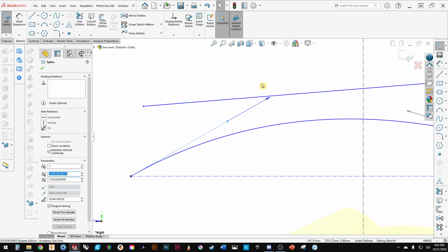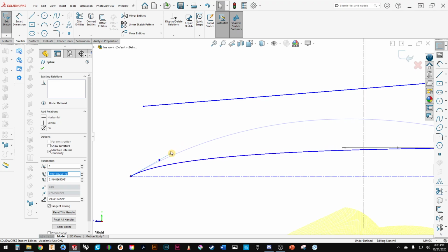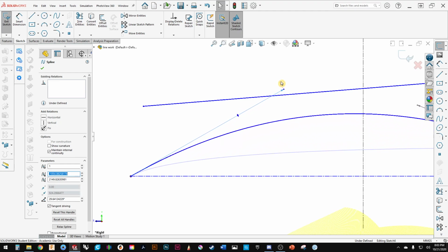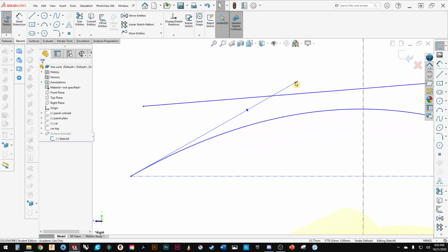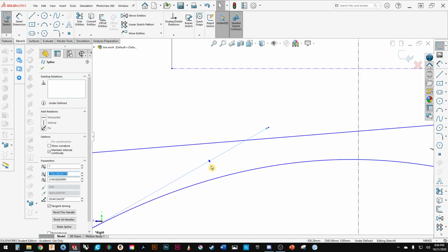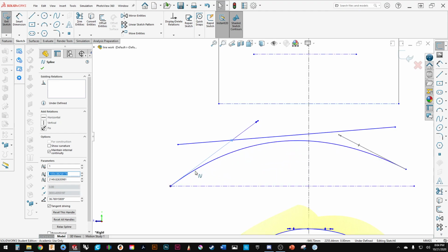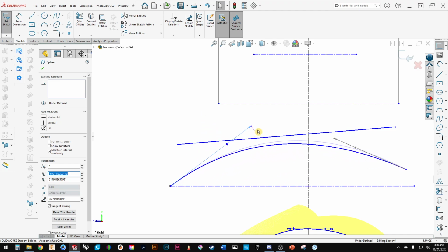Now, the next is I can adjust the length of the curvature. So you can kind of see here it's coming out. And you can see the curvature 1400, whatever. I can adjust that and drag it out. Now what I'm doing is I'm clicking on just the arrow. Clicking on just the triangle allows me just to adjust the angle. I can't do anything else other than the angle for that point. Clicking on just the arrow, I can't adjust the angle, just the length.